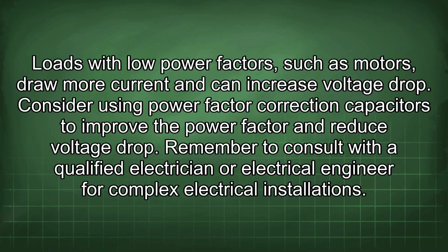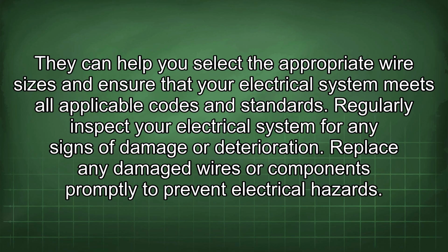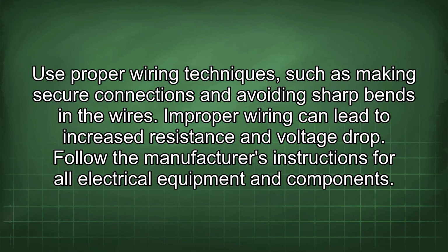Remember to consult with a qualified electrician or electrical engineer for complex electrical installations. They can help you select the appropriate wire sizes and ensure that your electrical system meets all applicable codes and standards. Regularly inspect your electrical system for any signs of damage or deterioration. Replace any damaged wires or components promptly to prevent electrical hazards. Use proper wiring techniques, such as making secure connections and avoiding sharp bends in the wires. Improper wiring can lead to increased resistance and voltage drop.